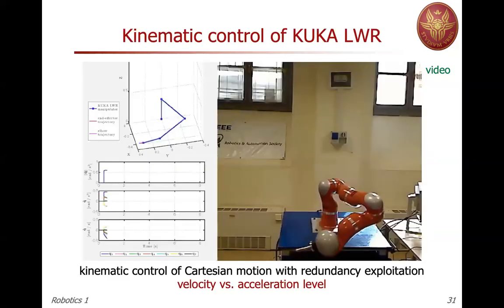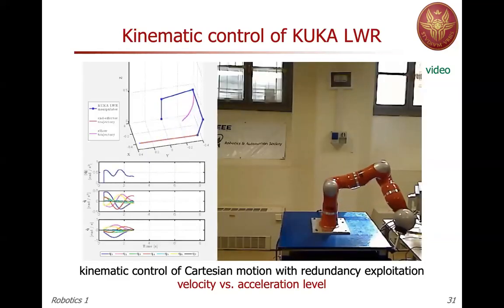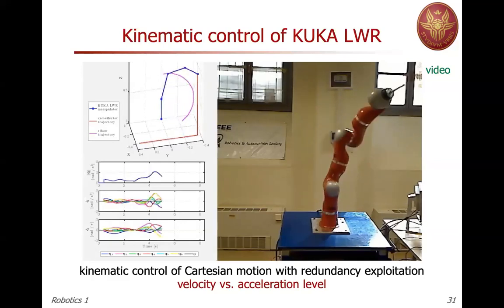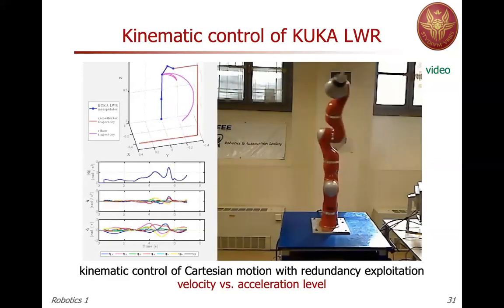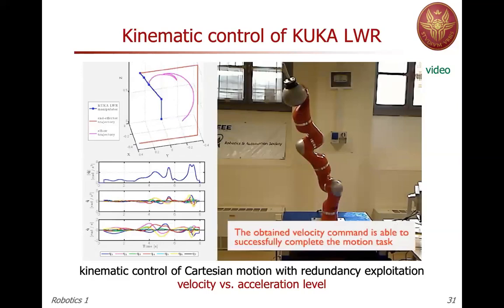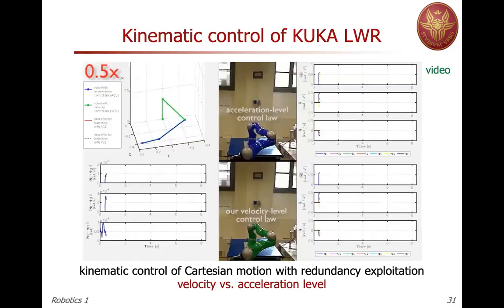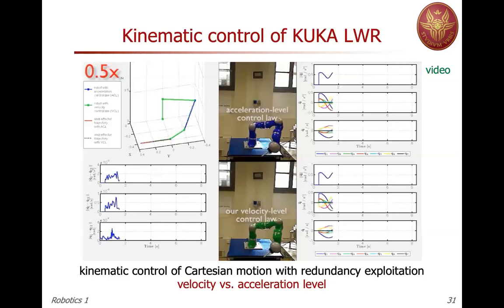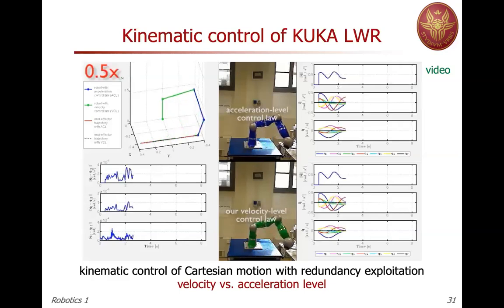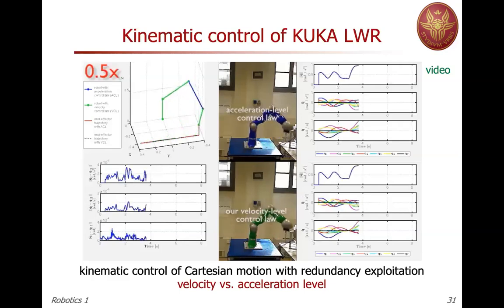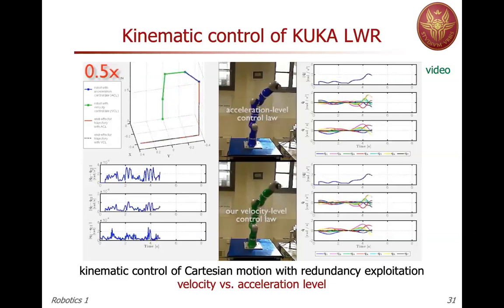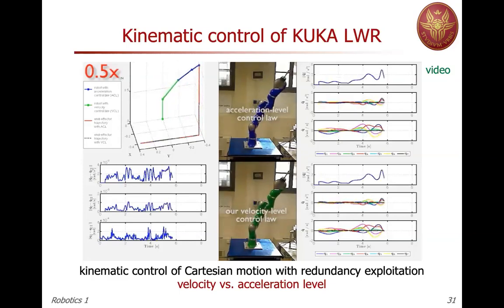Now, we would like to execute the same thing at the velocity level, but in a different way, trying to mimic what the acceleration command is doing, never exceeding limits that would bring the robot into a safety protection condition. Here you see the robot is orange, but you see the green and the blue version, which is the acceleration level controller, which works fine, but is more complex.